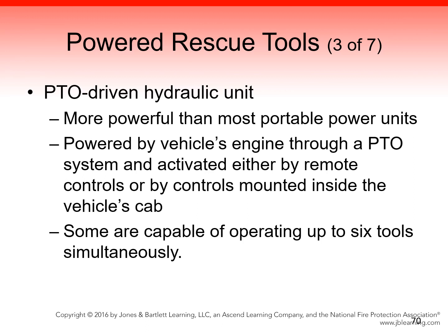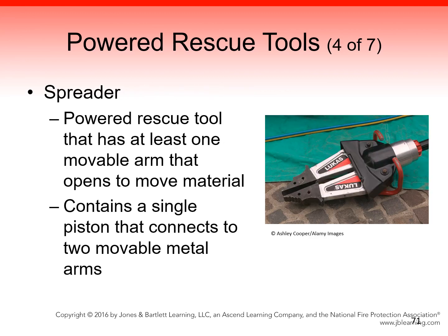Once the fluid is under pressure and traveling through the system, it operates as an actuator. An actuator converts the fluid pressure in the hydraulic rescue tool system into a mechanical force. This force is then used to operate one of four types of hydraulic tools. A spreader, shown in Figure 11-31, is a power rescue tool that has at least one movable arm that opens to move material. It contains a single piston that connects two movable metal arms.